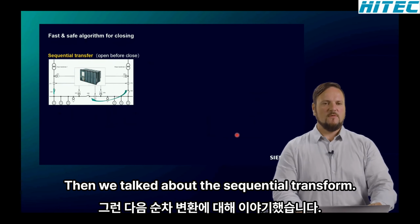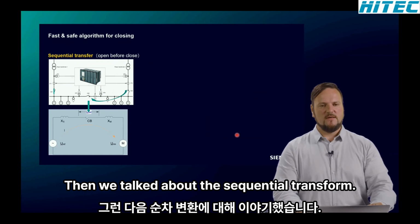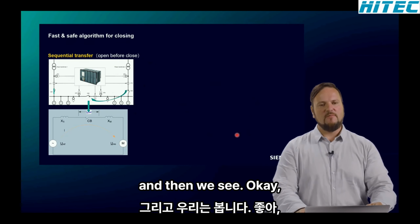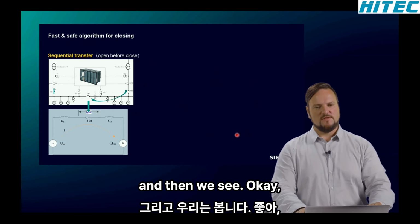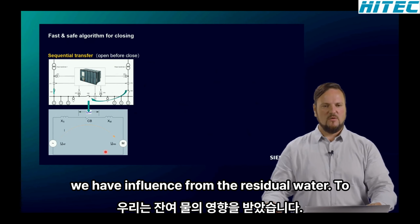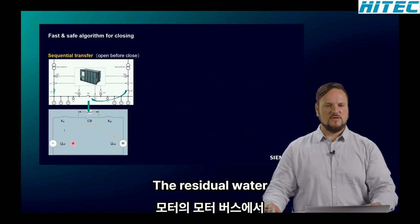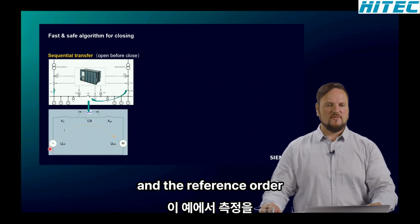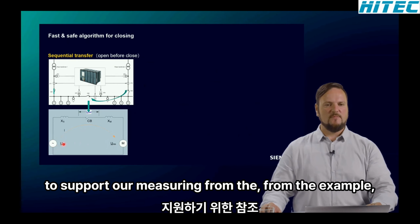So when we talk about the sequential transfer, we have to think about the equivalent of the circuit. And then we see we have influence from the residual voltage on the reference voltage. The residual voltage is the voltage on the motor bus, on the motor, and the reference voltage is the voltage which we are measuring from the alternative source, for example.